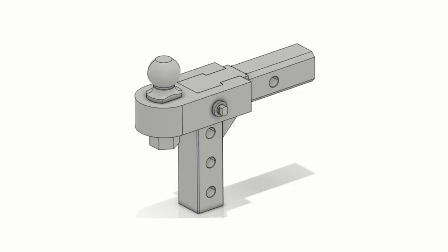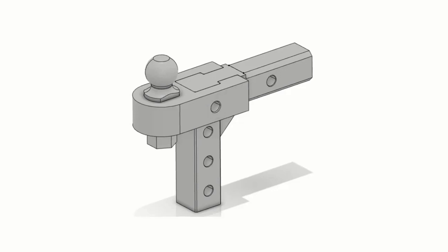First, let's remove the lock pin. We are going to replace the pin contact with the restraint acting in the X and Z directions. This will require us to create some geometry that we can use to create a group of nodes. We will also want to make sure the mesh follows this edge.